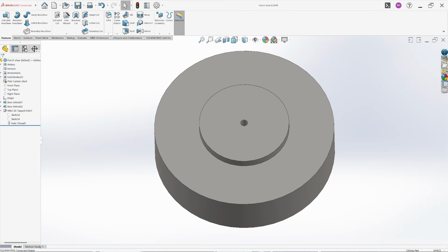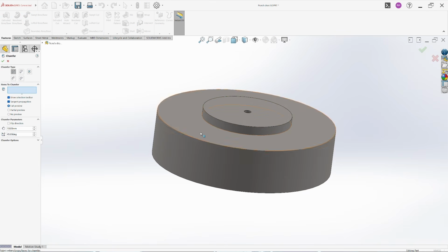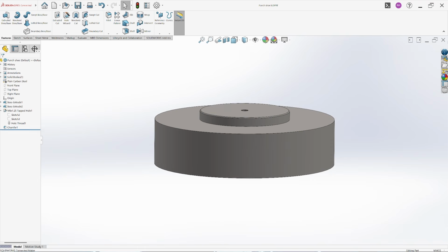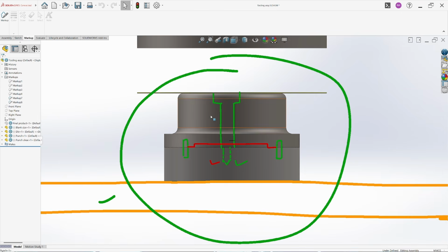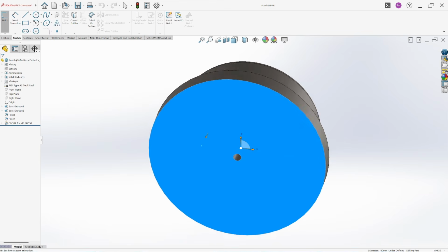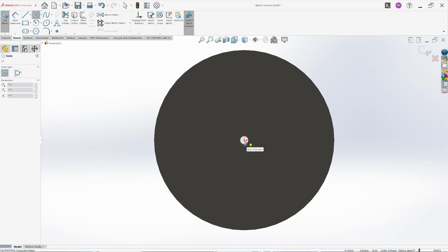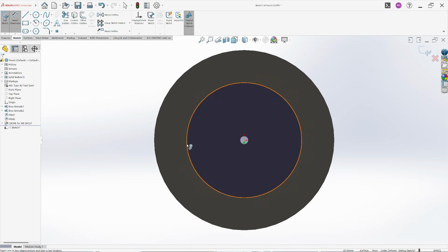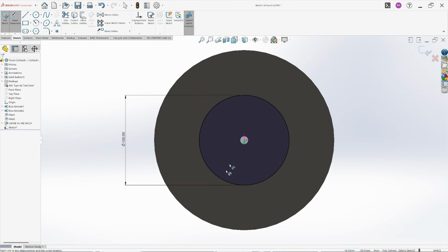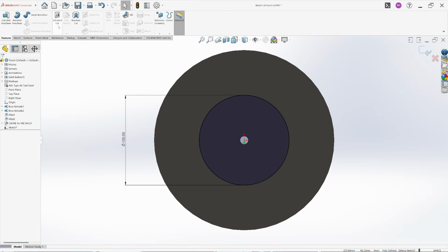Now we can also add a chamfer for easy insertion during the assembly. Add a 1 mm chamfer and let's save it. Okay, and let's get back to the assembly. Now open our punch and let's make the same step, but here we have to do an extrude cut. Let's set it to 100 mm. We will use an H7/g6 fit for that, and let's select extrude cut.